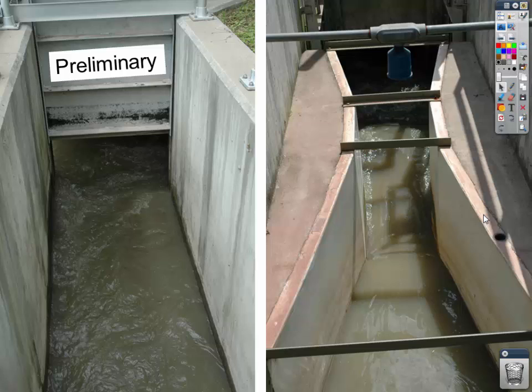Now, when you flush your toilet, the pipes in your house go outside and into the public sewage system. That system travels underground in a series of sewage pipes, and as it goes through town towards the treatment plant, those pipes are cut off from oxygen. There's no oxygen in those pipes. So our wastewater is on its journey in an anoxic environment. As soon as it gets to the plant, it enters preliminary treatment. You see it going in this concrete walled structure and under that little tunnel. That's the first time the waste actually hits the oxygen atmosphere.